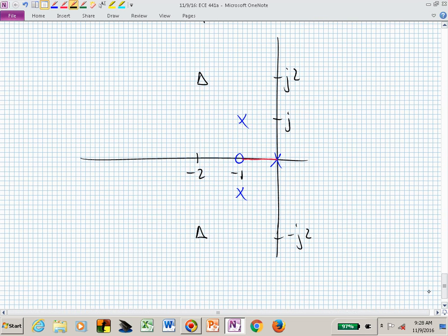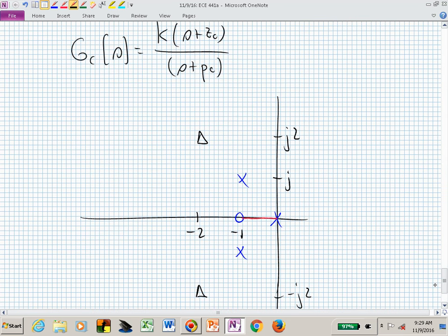How are we going to get the root locus to move to the left instead of going to the right to approach those original asymptotes? How do we sort of change the asymptotes? We now said we want this zero pole pattern and it's phase lead, so that says we're trying to put a zero somewhere here and a pole here.